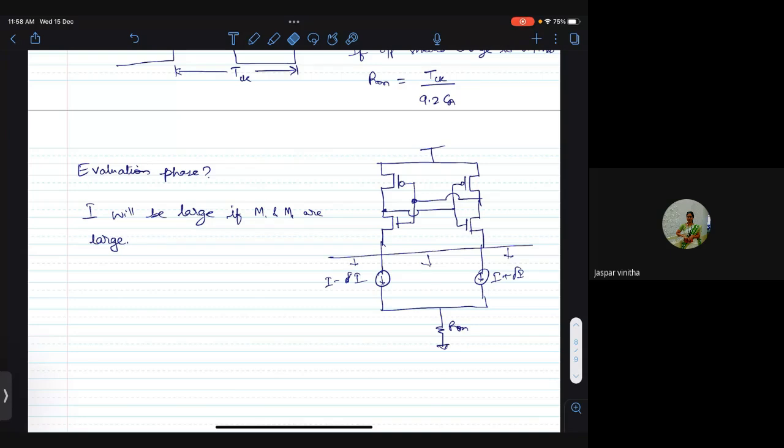Okay. Now the thing is, what should be R1? R1 is not very critical, the NMOS transistor here, because it just acts like a source degeneration for the input transistors M1 and M2. So it's a small on resistance which degenerates the source by a small amount. That reduces the gain of the input transistors by a small amount. That's not very crucial.